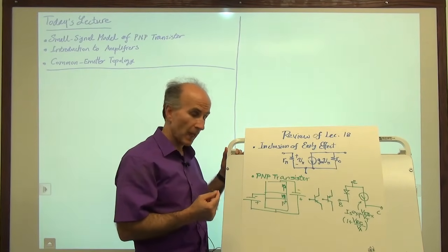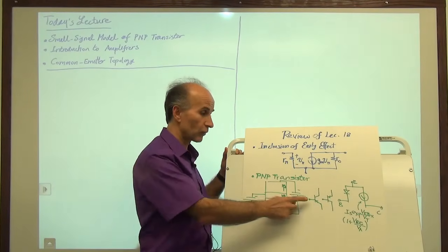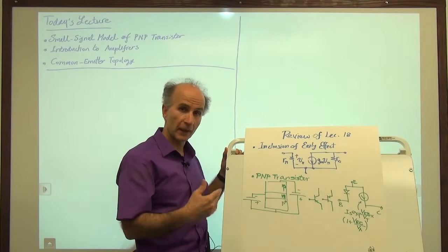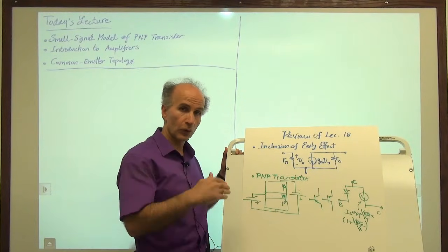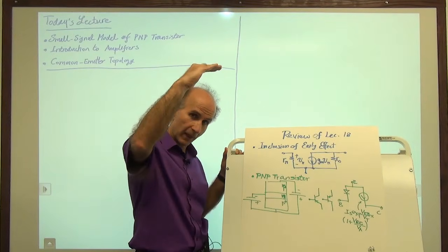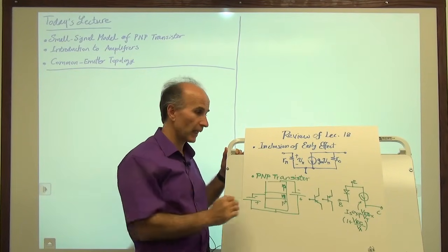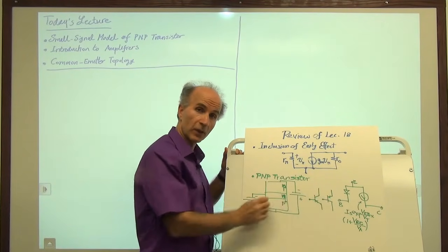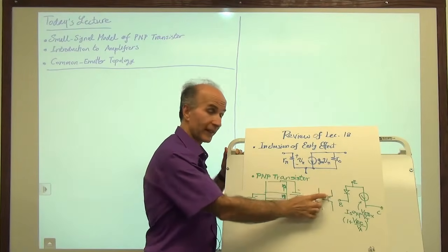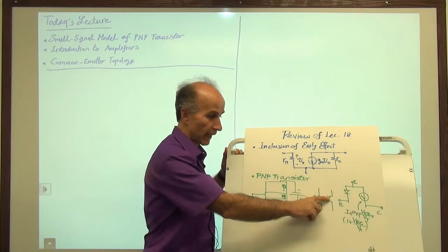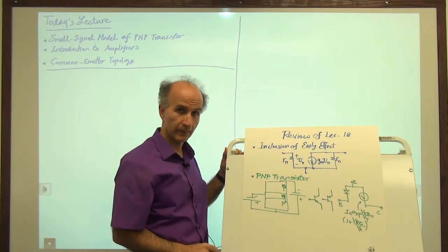device. And oftentimes we actually draw this device with the emitter on top because in electronics we would like to show positive voltages on top of the page and negative voltages on the bottom of the page. And this can be a source of confusion. So the top terminal is not a collector all the time. It just depends on whether there's an arrow on it or not.